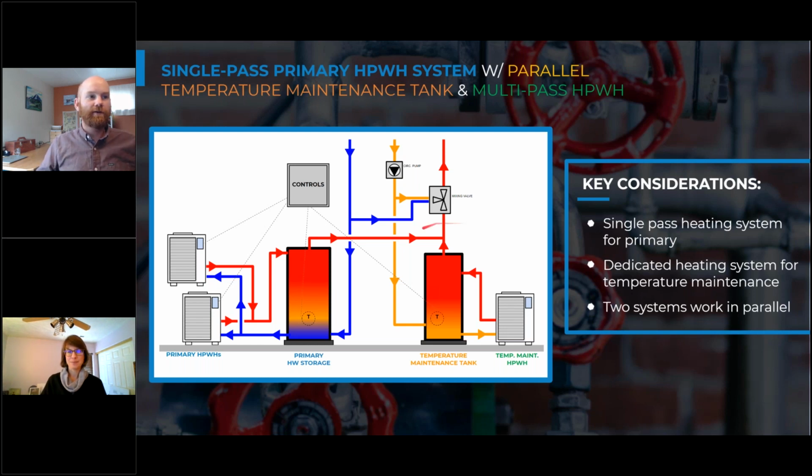Right. So we're storing water often at 140 degrees in these storage tanks, and so we want that water to go out at 120. At 140 degrees, it takes, I think, maybe 5 to 30 seconds to scald someone. At 150 degrees, it's only a second or 2 to scald someone. So we do have a concern with scalding, especially in our more sensitive occupancies like senior or young children in a school, right? We don't want to scald those folks, and they have slower response times.